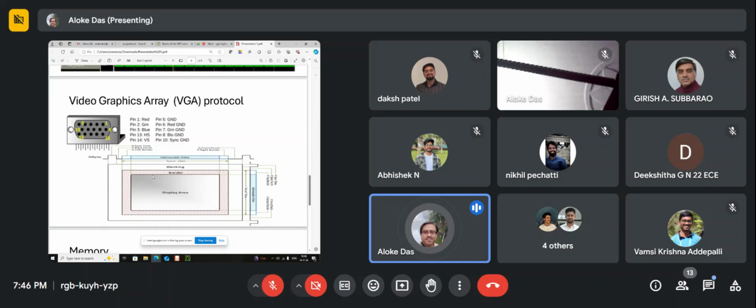So this horizontal sync, first it has to be 0, then it has to be up for some time. In the specification it is written, and that depends on the display also, like 540, 720, based on that, what is the value of this signal, how much time it should be up.